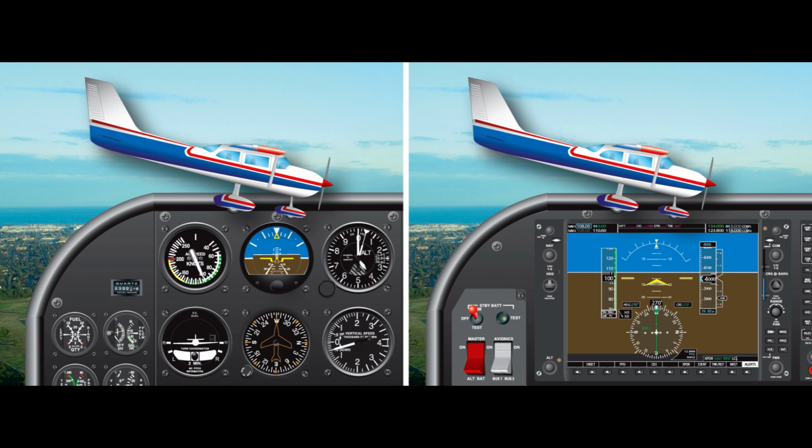Descent indications. The pilot should know the engine power settings, natural horizon pitch attitudes, and flight instrument indications that produce the following types of descents. 1. Partial power descent. The normal method of losing altitude is to descend with partial power. This is often termed cruise or en route descent. The airspeed and power setting recommended by the AFM/POH for prolonged descent should be used. The target descent rate should be 500 fpm. The desired airspeed, pitch attitude, and power combination should be pre-selected and kept constant.